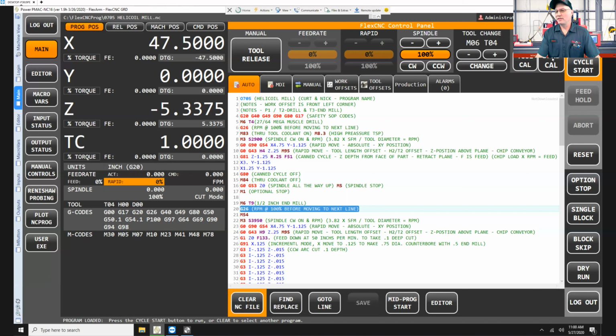The spindle calibrate is something you're not going to use too often. If something happens to the tool calibrating switch that you have to do something with, you know, the switch goes bad, coolant gets in there or something, then yes. If somebody crashes and you just kind of want to double check things, you can run the spindle calibration, and then it knows from home position how far down that tool setter is going to be.